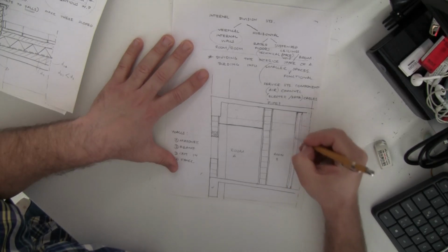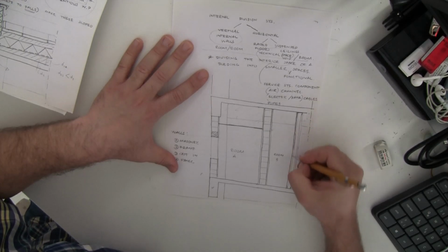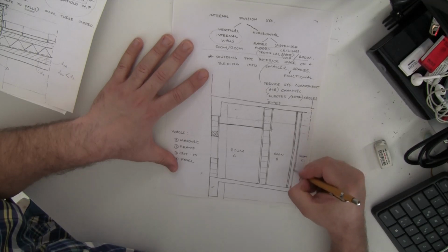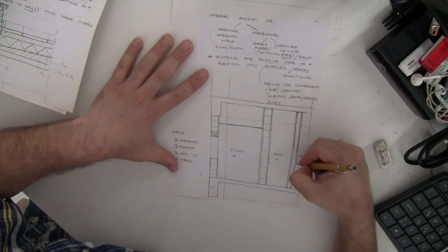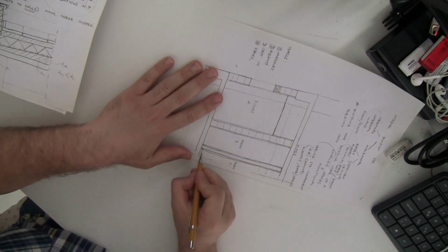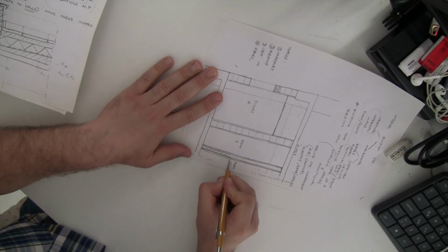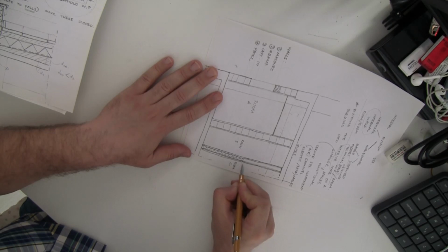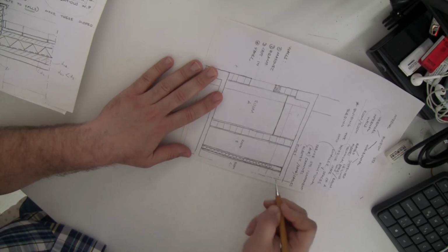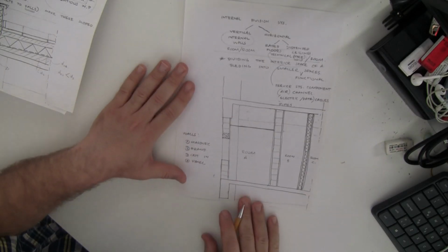Okay, and we are going to cover both sides of it with a board. 90% it will be a gypsum board. In order to make its acoustical performance, we are going to fill here with glass wool blanket acoustical insulation, like that.